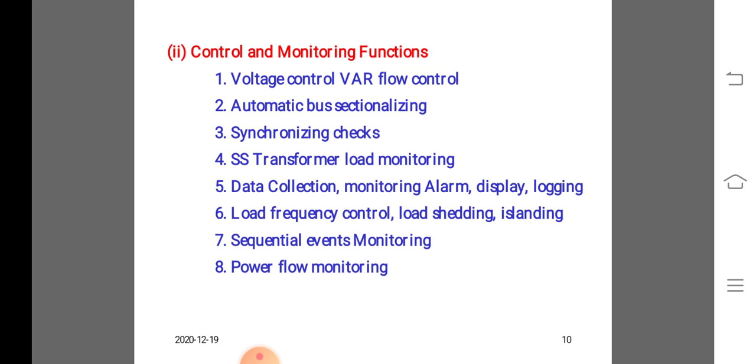and therefore it is not applicable in some cases. A more recent development has concerned the use of fiber optic cable, a technology capable of extremely fast communication speed. Although cost was originally prohibitive, it has now decreased to the point where it is viable. Fiber optics may be either run inside underground power cables or they may be fastened to overhead transmission line towers just below the lines. They may also be run within the shield wire suspended above the transmission line.